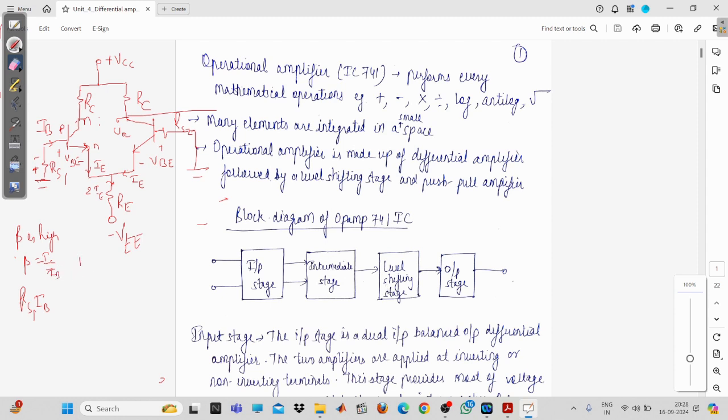So in that case you can see this IC is nearly equal to IE, because if you are doing the DC analysis, it means that you will be requiring the operating point. Fine. And normally to locate the operating point and to make the operating point stable, we are doing this DC analysis. We need to find out what are the operating conditions of the transistor. Fine. Because beta is selected as a very high value, you can neglect the value of IB.